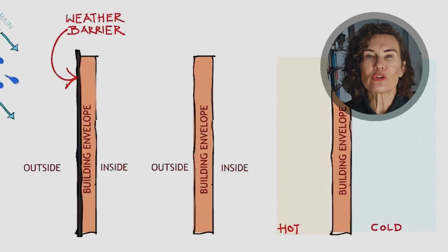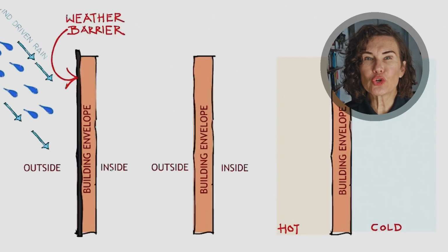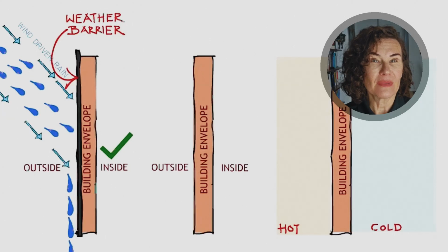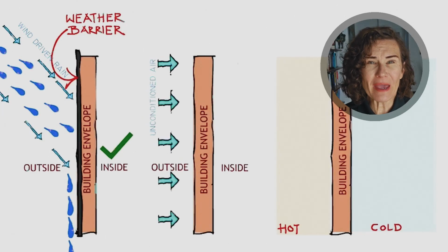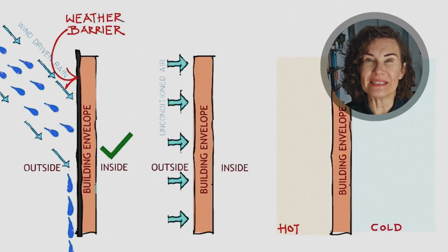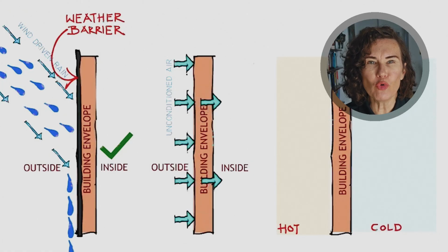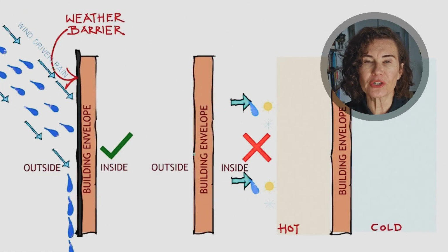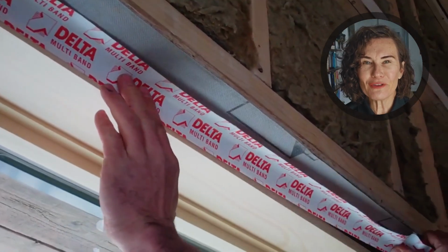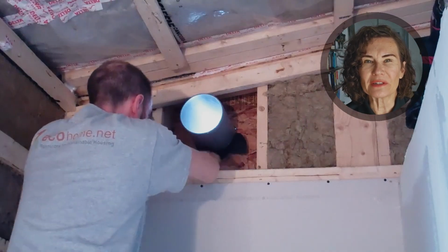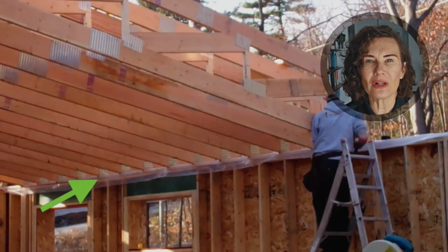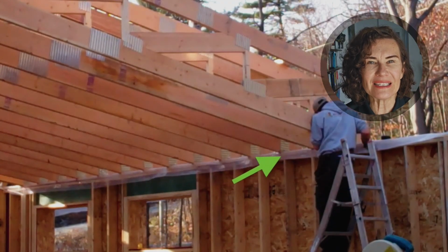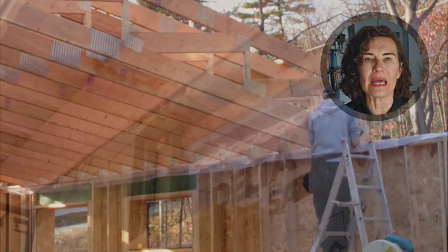You learned that controlling air movement is crucial, and that's where air barriers come in. These aren't the same as vapor barriers. They are designed to stop the movement of air, which carries both heat and moisture. You explored different types of air barrier materials and learned how to install them properly to create a continuous airtight seal around the building envelope.